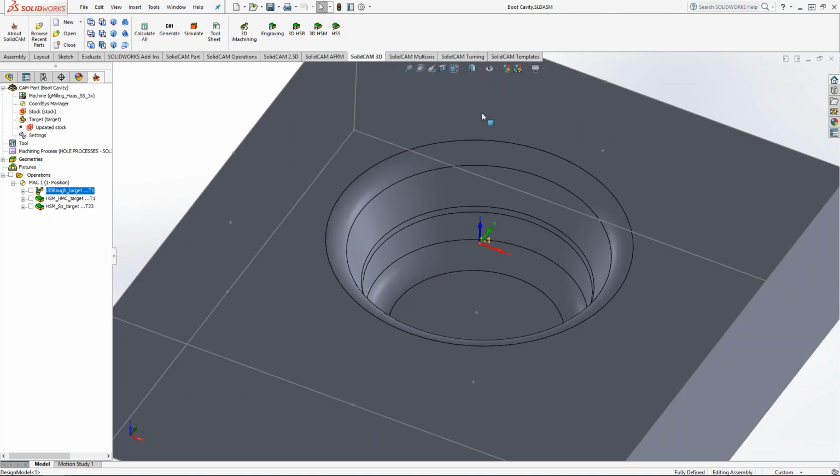Some, we'll call them the cheaper tools, we did out of 4140 pre-heat treated. So everything was pretty, I won't say real hard, but anywhere from maybe 28 Rockwell C up to maybe around 50 or 55 Rockwell C for wear for certain materials.